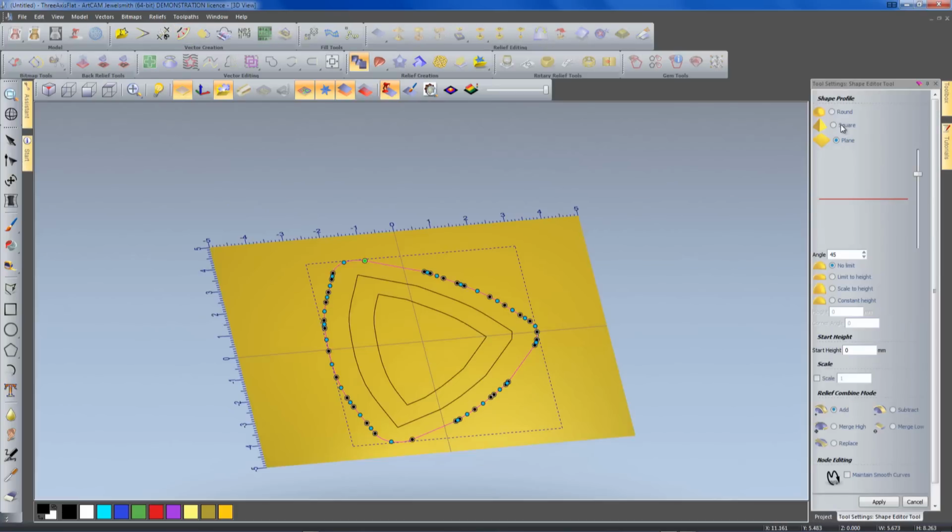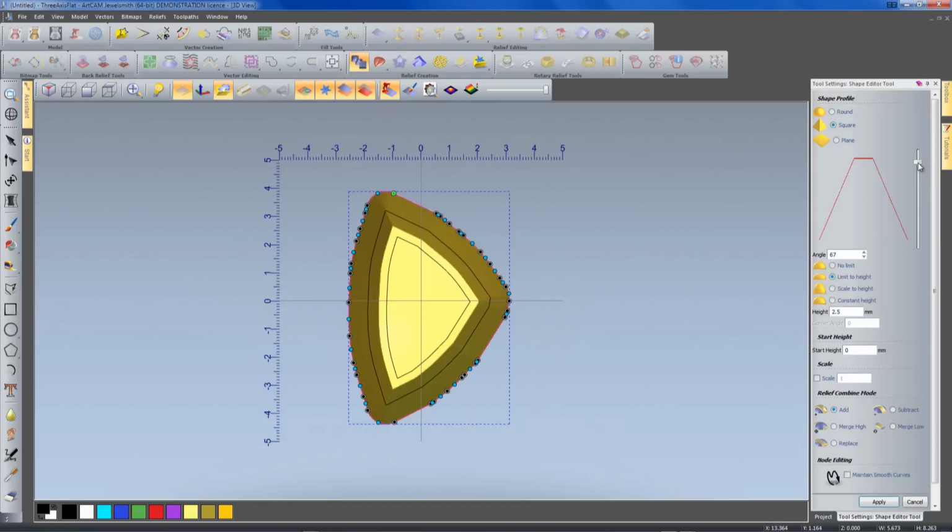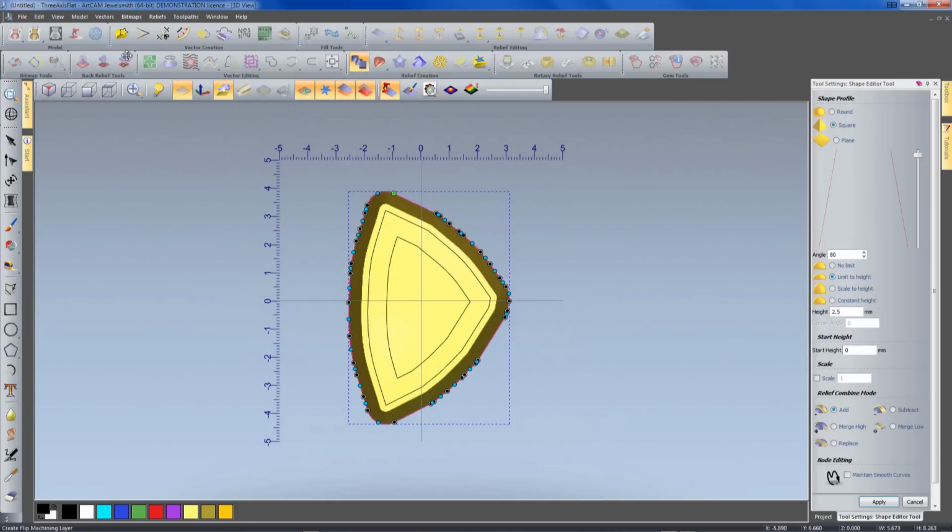Use F12, like I say, and start shaping this from the top surface. So we want something about 2.5 this time on that top section. Looking directly down from Z, we want this to give us a nice setting edge just outside of the actual setting edge for the gem to sit inside. Before I do that, I'm going to go back to the model.